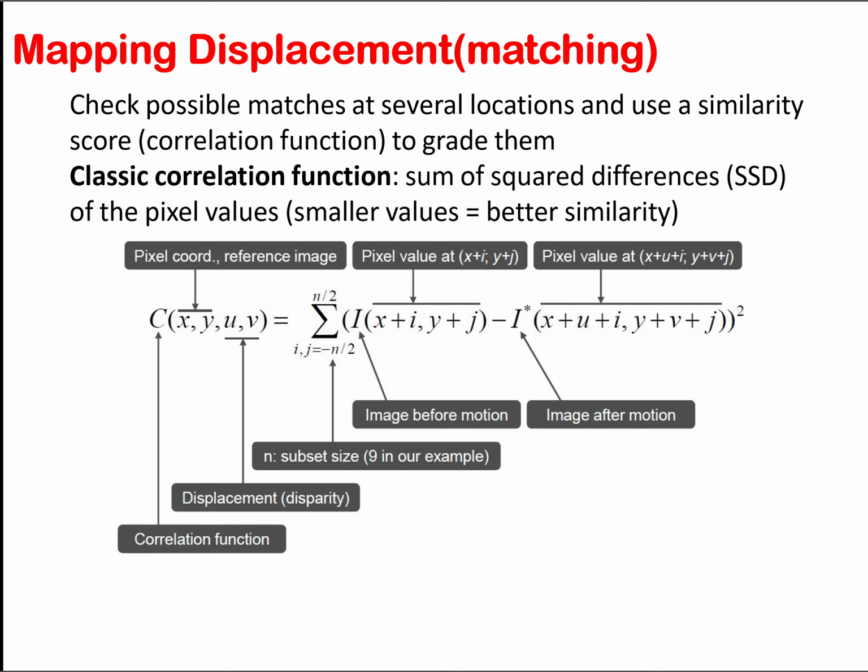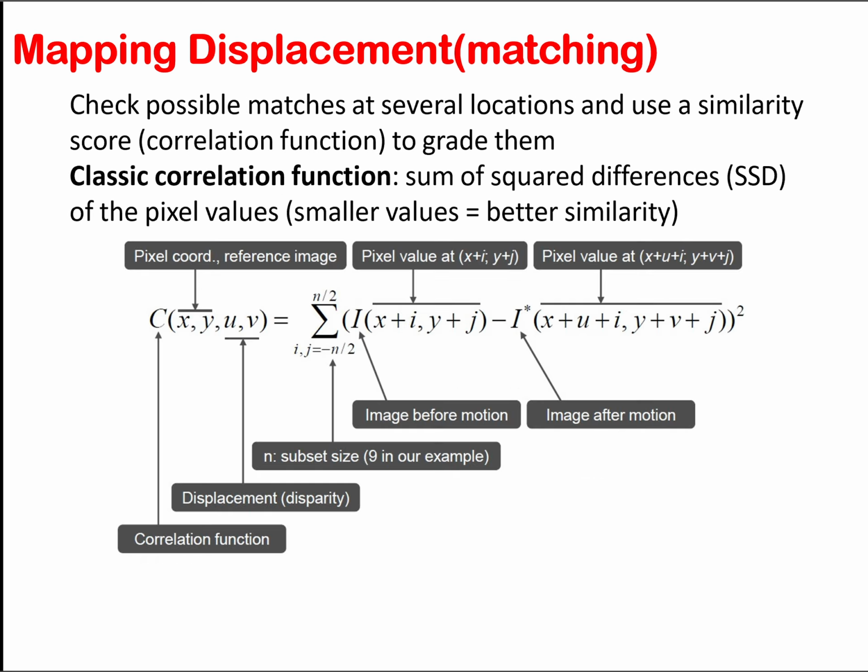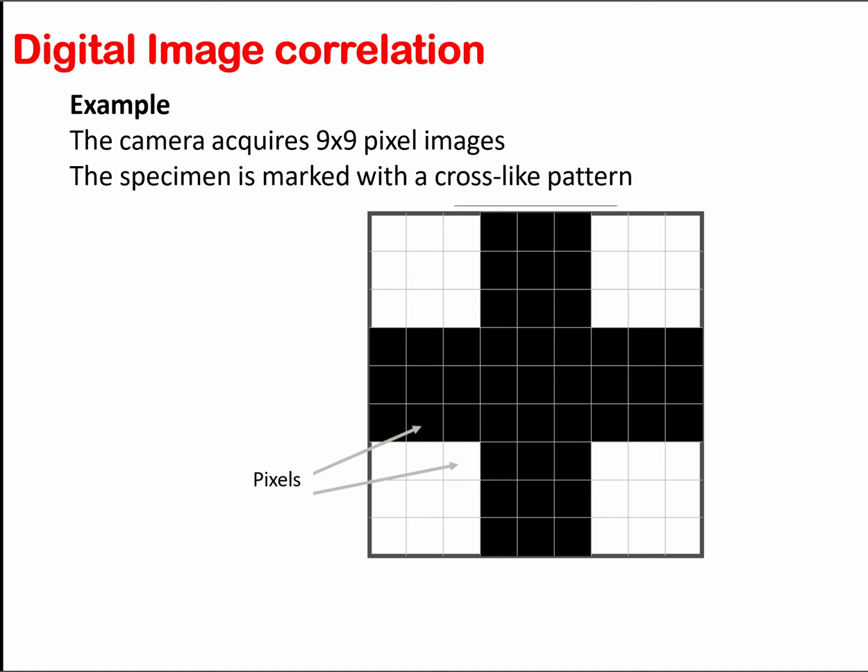All of the points of interest, all of the field of interest, right? And it's going to give you a pattern like this, which is a heat map. The red is going to give you the highest amount of strain, and the blue and the darker zones are going to give you the lowest amount of strain. This is what we want to get out of it eventually.